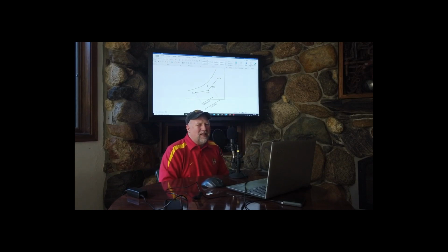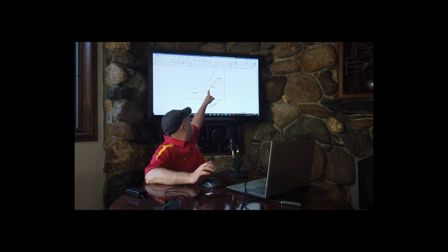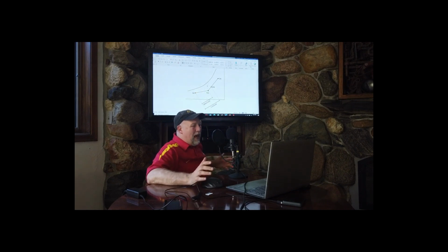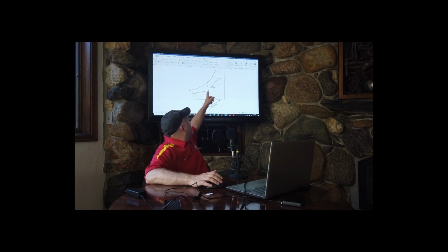It'll be just a little drier. This return air point is just the space condition. The difference between the two is our total space load. Notice, most of that is sensible, and there's just a little bitty bit of latent. Right? We only calculate the sensible load, though.